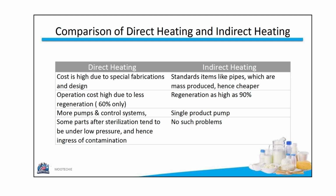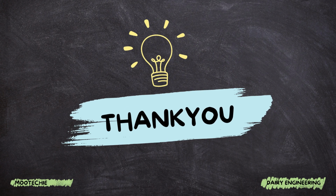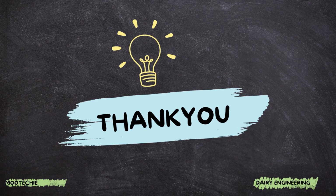Indirect heating uses standard, cheaper components like pipes, allows for high regeneration up to 90%, often uses a single product pump, and has no low pressure contamination risk. Thank you for joining this comprehensive session on UHT processing and aseptic systems. Understanding the differences between direct and indirect heating is crucial for selecting the right technology for producing high-quality, shelf-stable dairy products.